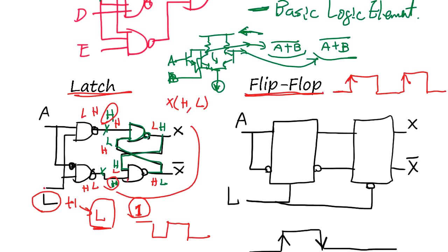When you make it edge control, then each clock cycle you can update the logic into the flip-flop. So this is latch and latch, and A is driving negated A, the latch, and the latch output directly goes to another latch. And the trick is to have the latch control in opposite polarity into two different latches.